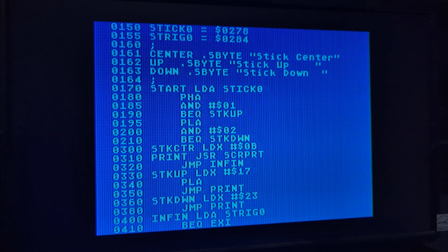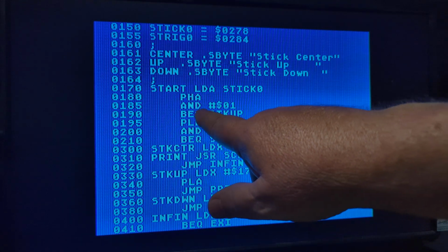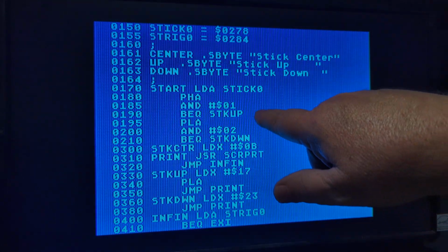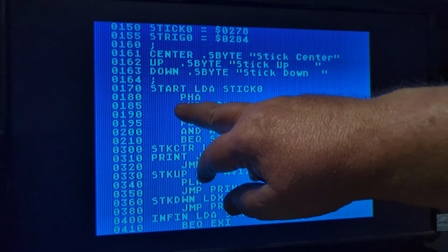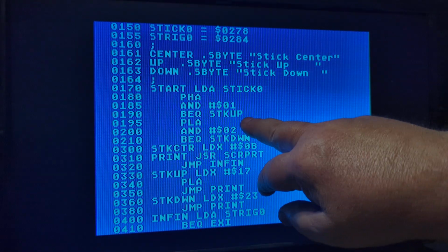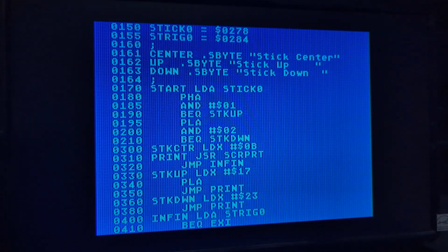All right, so the last thing about the joystick program is, I believe it was Brian, not Carl, as I said in the first time I recorded this video, who said, so originally, the whole reason we're using a variable, right, is because the AND is a sort of destructive thing that changes the value in the accumulator, so we wanted to store it, so after the AND destroyed it, we could get it back again and check it if we had to.